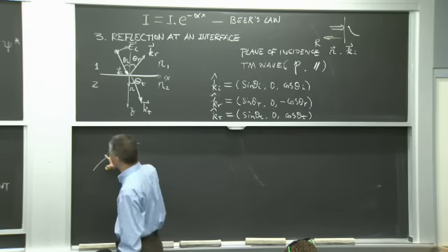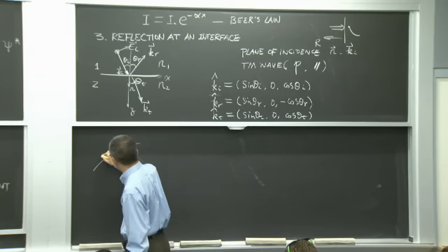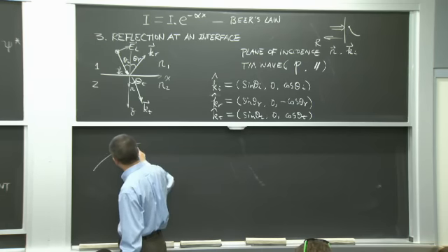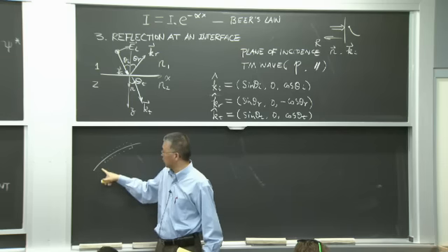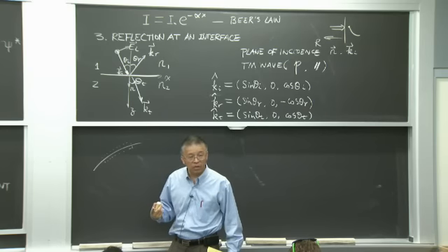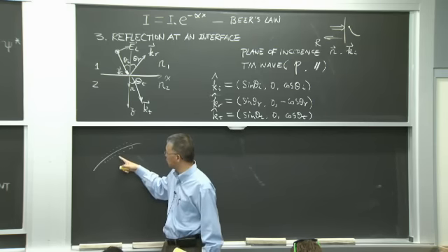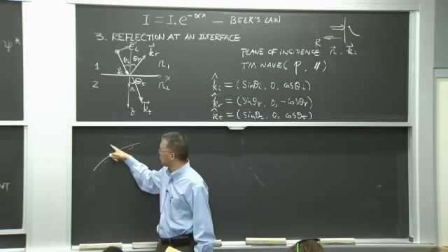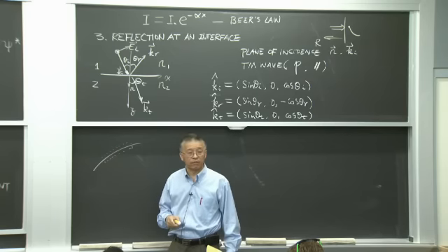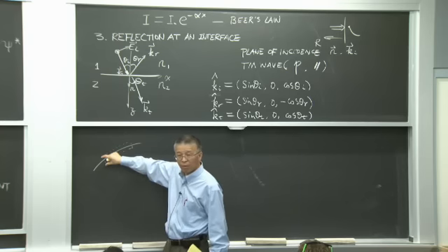Many of you are probably more familiar with heat transfer. So while I try to write down the boundary condition for this, if this is a liquid, this is solid, right? I'll apply the energy conservation. I say on the solid side, the heat conduction coming towards this interface equals the convection going through the other interface. I'm applying the first law. The thickness is 0, right?